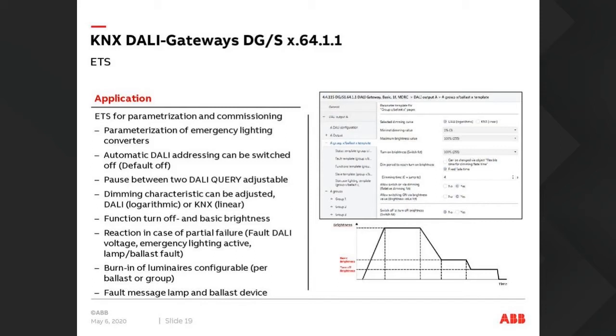Another interesting setting in here is the pause between DALI queries. I've seen a couple of jobs, not many, where we query a lamp fitting. The way DALI works is that it's constantly polling the DALI line. It'll poll every device one after the other. First of all, it polls the status: do you exist? If you exist, then tell me are you turned on or off or what level you're at. So it will constantly poll the whole network.